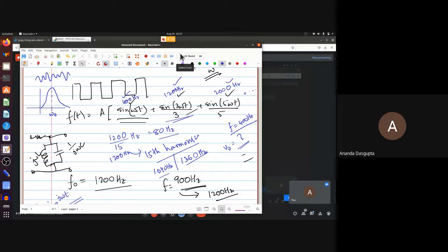So in the lab, this particular setup is actually used. Not only this particular setup, the problem that I gave you essentially is a standard lab problem. In the lab, we call this determination of Fourier series, but it basically is using a parallel resonance circuit to pick out different resonance frequencies.